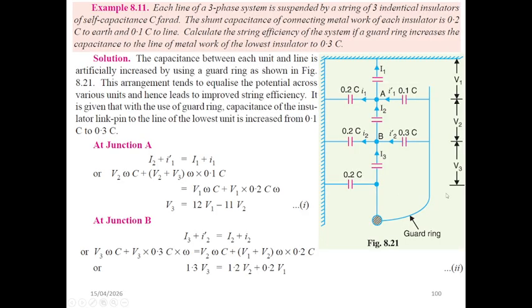This is another example which focuses on improving the voltage distribution and string efficiency again. Similar to the previous one, but we install a guard ring here.